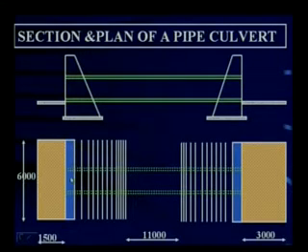This particular one is nothing but the head wall. As you see from the top, this is how it looks. You have a head wall on one side, the head wall is also there on the other side. Now what is this? This is the apron on the downstream side. Usually the width of the apron on the downstream side is more because the velocity of the waters are more at the exit. Here on the upstream side it is 1500, here it is 3000.